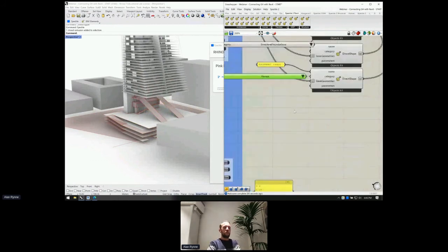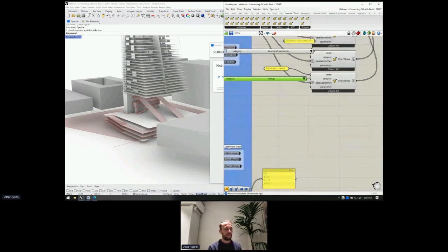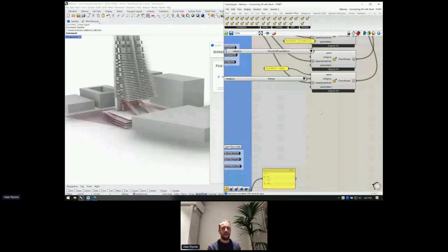If some geometry is not supported, what we usually do is we fall back to either its mesh representation or its curve polyline representation, which is usually supported across the whole environment. So sometimes you will send a super nice, complicated solid that you have on Rhino, and you will end up getting a mesh in Revit due to limitations on the API and also some improvements that we are pending. But mainly limitations of the API.